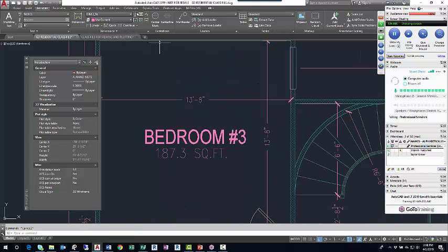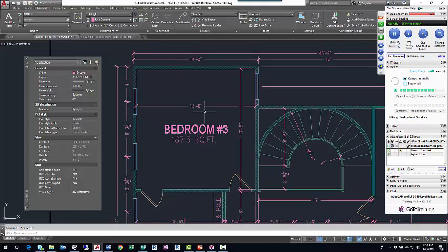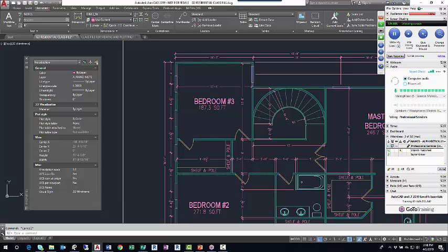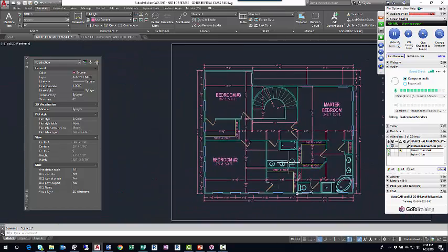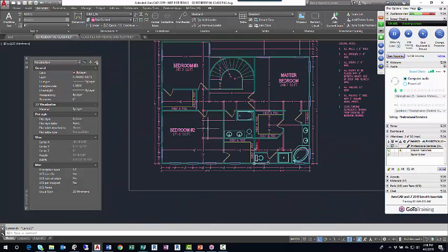Here's another place I can break. I'll go break, click the horizontal, click the vertical. With that break, there's no rule you always break the horizontal. I'm trying to be consistent. So where I've broken the horizontal in one place, I'm trying to always break the horizontal. Or if I broke the vertical, I'd want to continue to break the vertical and so forth.